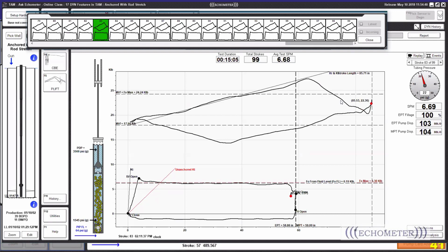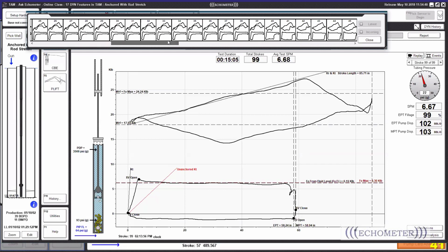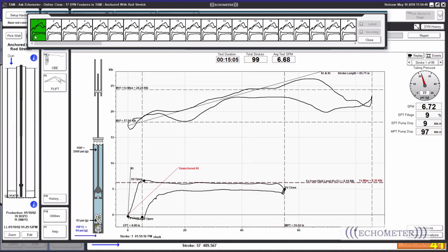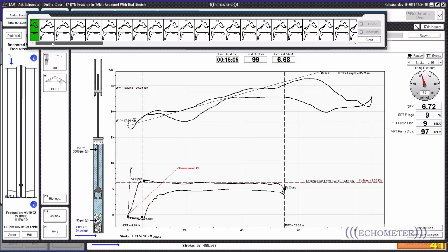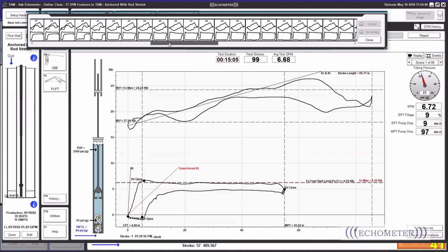So it looks like we're having a full pump, but if we review this well, actually the well was coming with a really pumped off condition. And one of the benefits that you can have by acquiring continuous dynamometer data is you can catch these kinds of behaviors in the wells. If you collect one dynamometer card from a PRC, that will be one single card. You won't be able to see the difference. Of course, we were lucky to catch the behavior in this well.